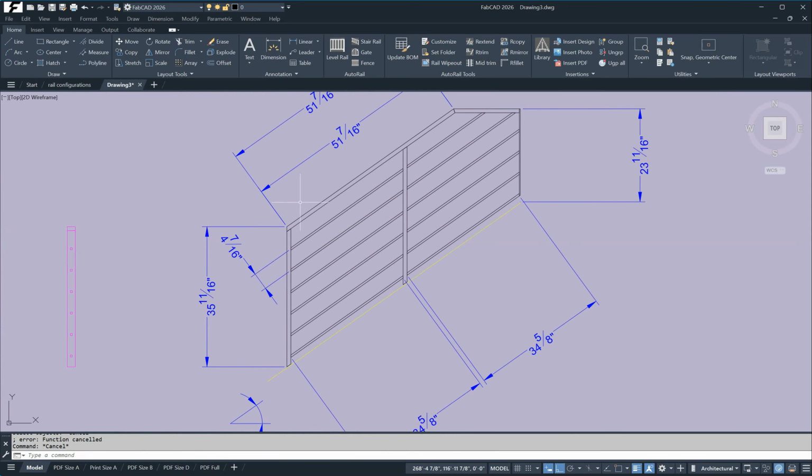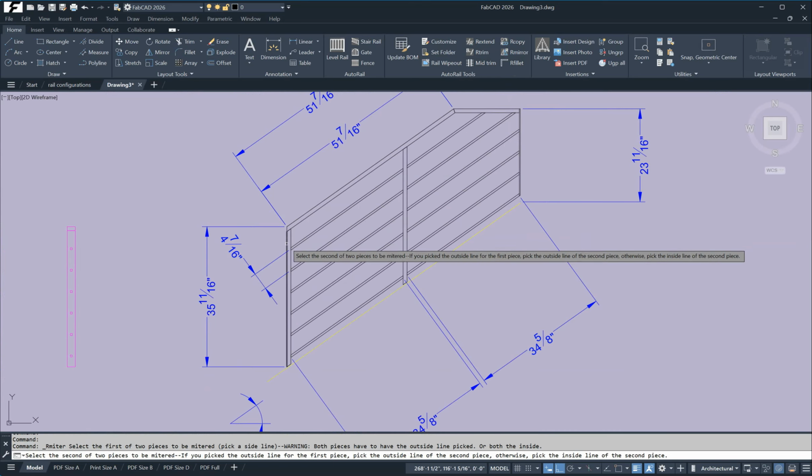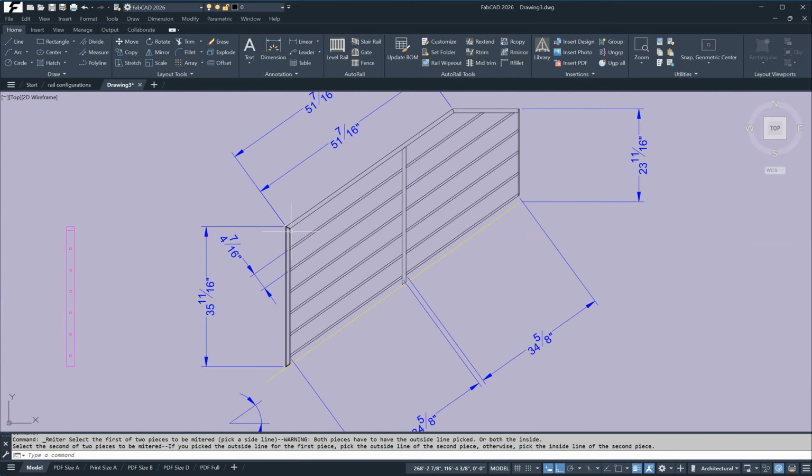And also if I want to touch it up additionally, I set it for a butt joint because of the strap. If I don't want a butt joint at the bottom, I want to miter it, then I use the R-fillet command here and create my miter joint at the bottom.